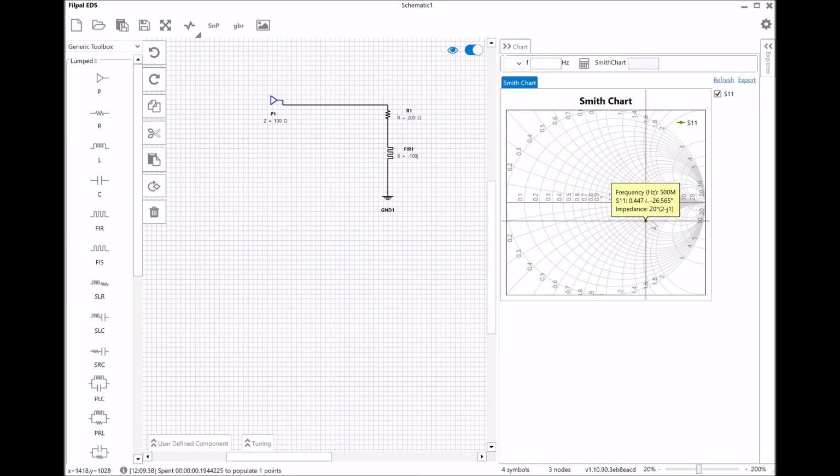So obviously you can see here it is at the lower side, which is the capacitive region. Now I want to do the impedance matching, means that I have to add a section in between here, so that when I look into this point will move to the center, which is the place where you can see that this is purely real at the value of 100 ohm.